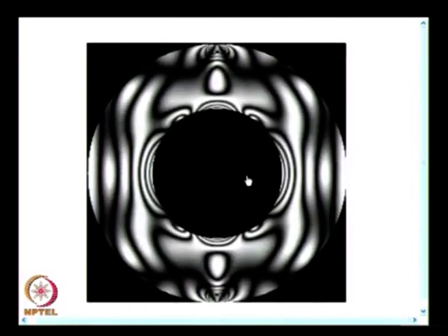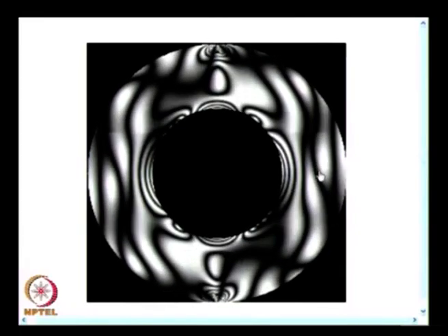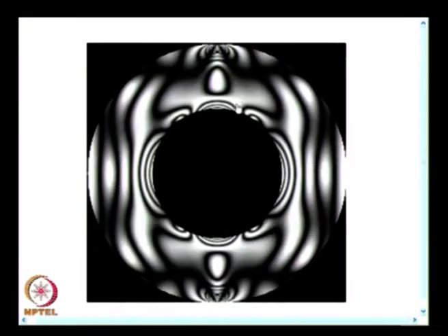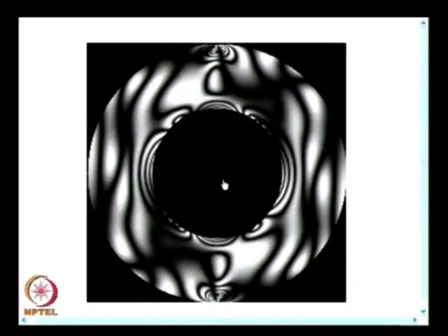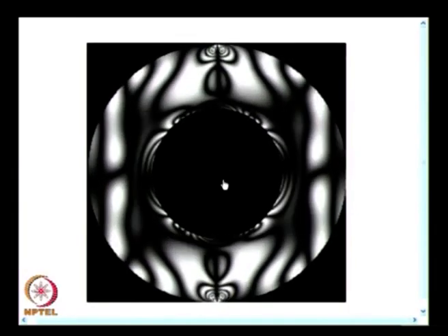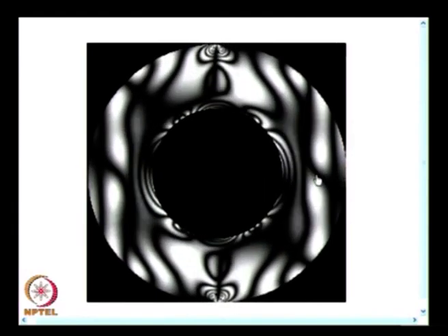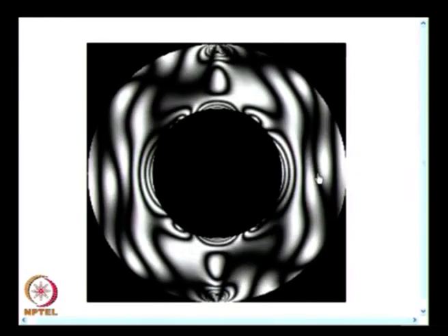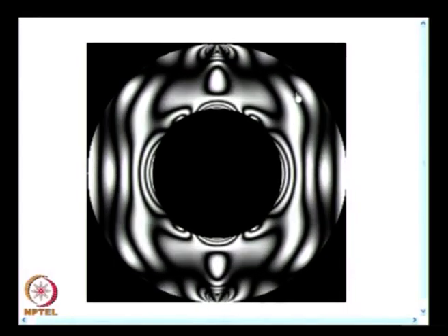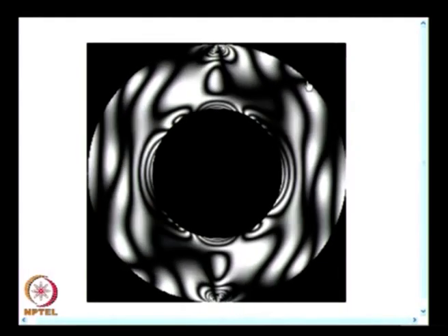The isoclinic actually rotates in an anticlockwise direction. I have all the isoclinics pass through the point. Do you not find that? Because here I am continuously rotating the polarizer analyzer combination, crossed, and what you find is, you always have an isoclinic passing through this point of interest, and you also find the 4 points which I said on the outer boundary, here also all the isoclinics pass through the point of interest.